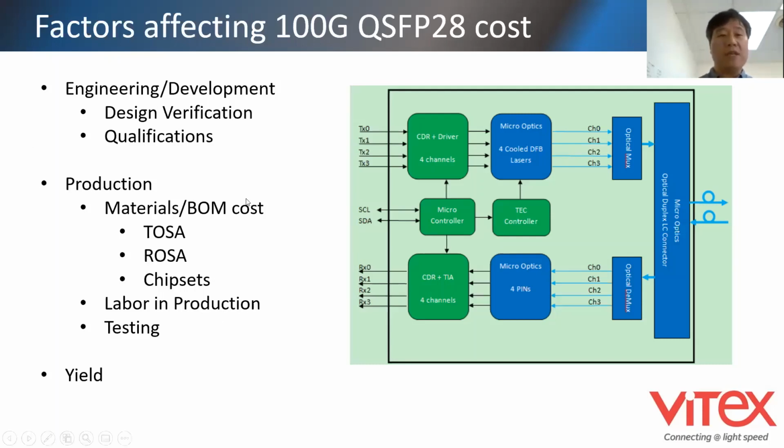And some of the key phases, this is not the only one, but as some of you can appreciate, the main phases are design verification and qualifications, making sure of the reliability, temperature cycling, storage, even the package drop test, all of the standards that you want to follow. So those definitely play a role in the expenses of developing the module.